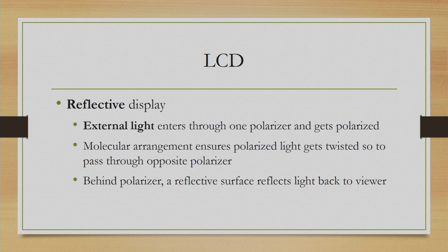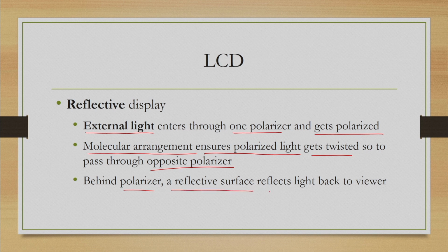In case of reflective display, we have external light enters through one polarizer and gets polarized. Then the molecular arrangement ensures that the polarized light gets twisted so that it can pass through the opposite polarizer, and behind polarizer a reflective surface reflects the light back to the viewer. So, here it depends on external light.